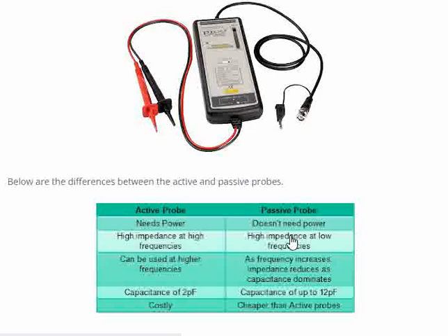But the quality of the passive probe, which is used at low frequencies, is very good. And the major disadvantage we can say for the active probe is the rate at which it fails. It needs to be handled very carefully. There are many chances of an active probe getting damaged, whereas a passive probe is rugged.